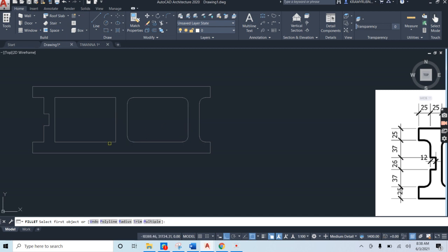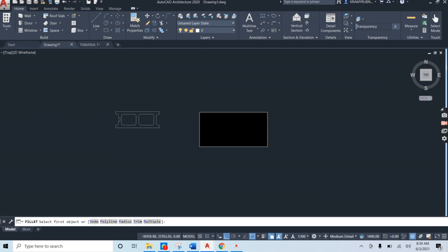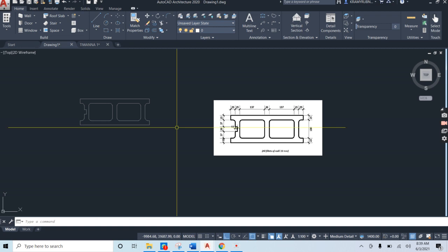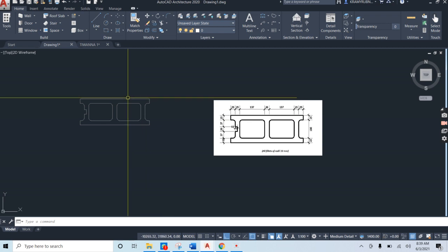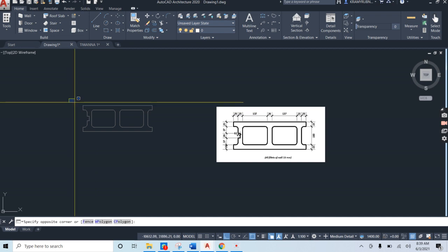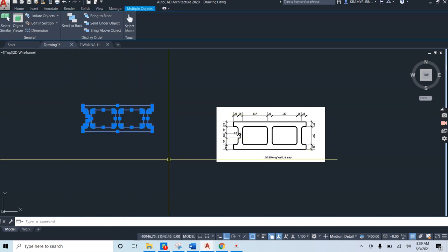My pick box is a little small, hence I'm moving a little bit slow, but I'm getting there. And finally, these two, you should be moving a lot faster as practice increases. Now, what you will notice is that currently my block, or the features of my block, is still pretty much in single lines. Let us select our entire object and do a J, enter, for our object to be joined.